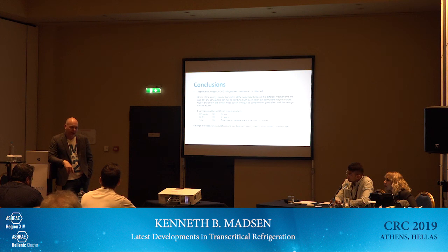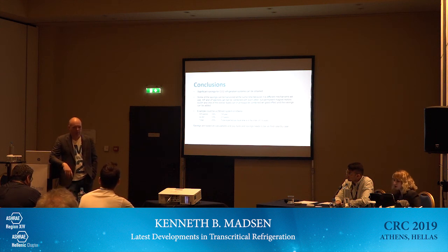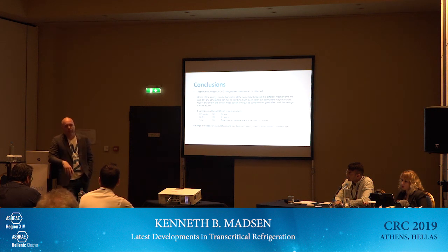And I think most places we would also be able to compete with them in hour-to-hour COPs. There are some places where it's awfully hot. When we do racks for Portugal, for instance, it's 44 ambient, and then the efficiency of CO2 is not as high as we would hope for because we have some limitations on pressure. So there we suffer on efficiency when it's 44, but that's only, let's say, 3 days a year. So in the total picture, it really doesn't show up.